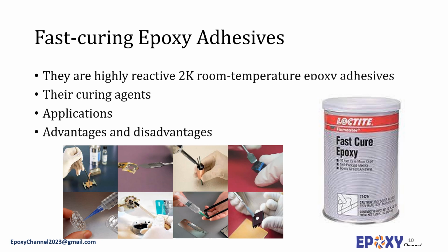In the commercial 5-minute epoxies, mercaptan terminated curing agents and amine catalyst accelerators are often used. Fast curing adhesives can be employed to bond difficult to clamp fixtures, for example, surface mounting electrical receptacles, brackets, and racks, or for rapid production line assemblies, for example, for bonding sections of reinforced plastics car bodies. They are also of great importance for applications where time matters, for example, for emergency repair of leaks or for bonding traffic buttons to highways when minimum traffic delay is essential. Fast curing epoxy adhesives are quite suitable for cold weather construction uses.